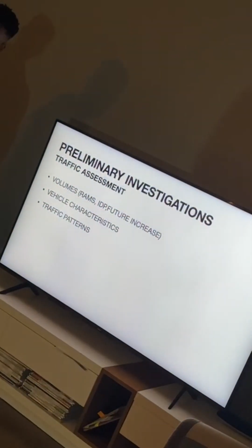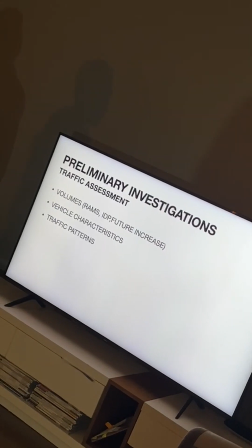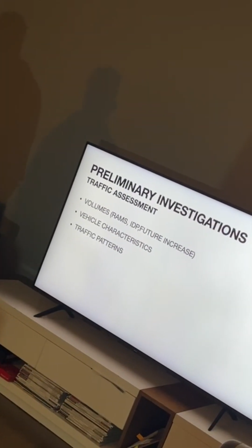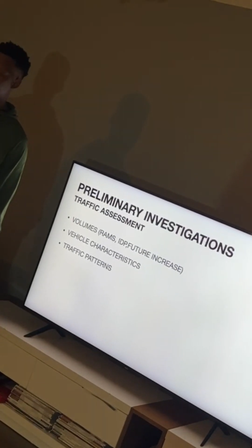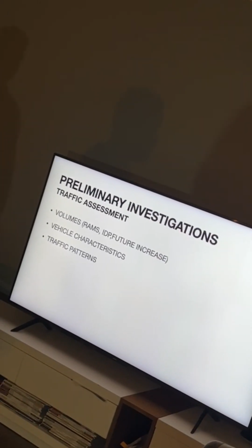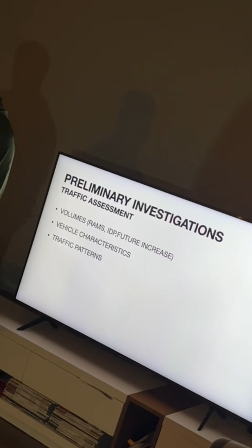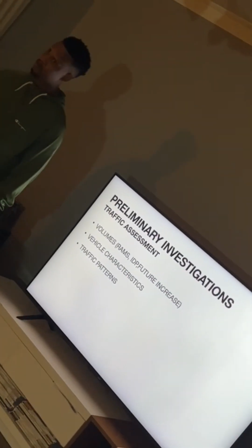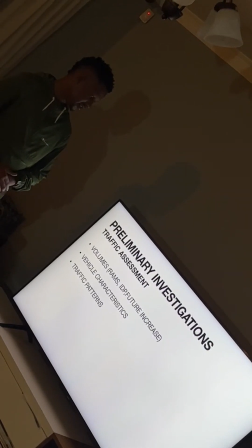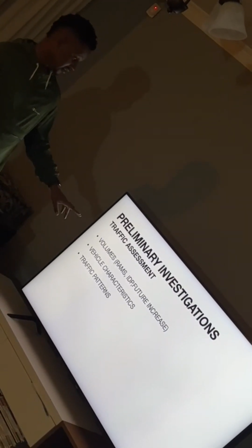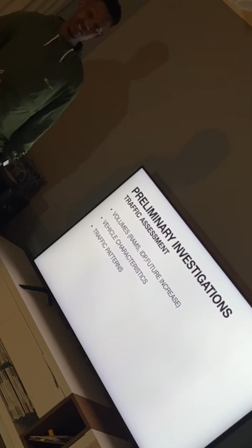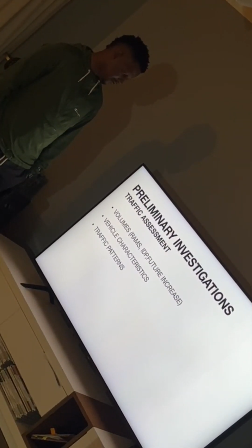Traffic assessment. Traffic counts were conducted. Over and above that, they were also correlated with RAMS. RAMS is the Road Asset Management System, used by government, where we've got information such as the traffic volumes. The IDP was also considered, which is the Integrated Development Plan of the municipality, where it was noted that there are future developments that the municipality is envisaging for the area, and these are going to affect the future traffic volume. So there's an anticipated increase in traffic volumes.